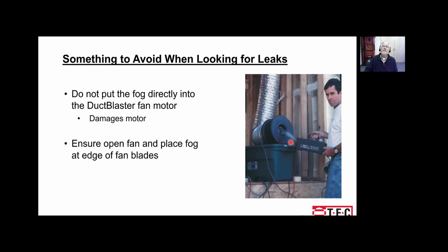We tell people that if you do this, ideally use a different kind of fan. Use an inline duct fan or some other kind of fan. But if you do use the duct blaster fan, take all the rings off and try to inject the fan way out at the edge of the fan so that all of the smoke just hits the fan blades and does not get into the motor. And in most cases that works fine and doesn't seem to damage the fan.